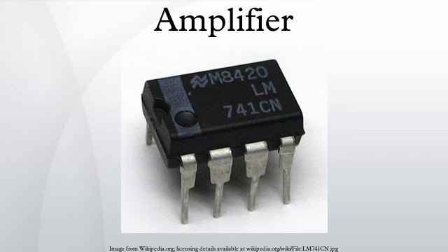An amplifier that is said to have a gain of 20 dB might have a voltage gain of 10 times and an available power gain of much more than 20 dB, yet actually be delivering a much lower power gain if, for example, the input is from a 600 ohm microphone and the output is connected to a 47 kΩ input socket for a power amplifier.